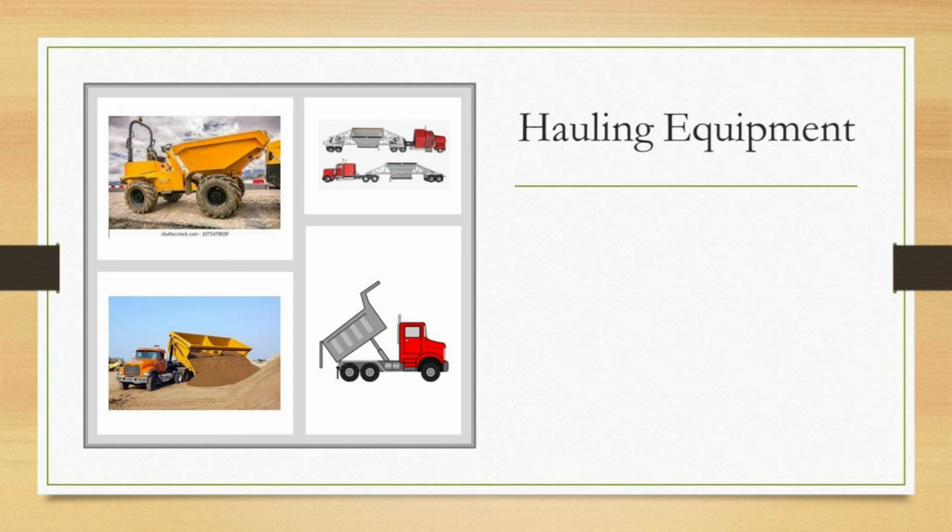Equipment used for transportation of material is known as hauling equipment, or simply haulers. Haulers may operate on roadways or railways, and are also involved in transportation of building materials, carriage and disposal of excavated earth, and haulage of heavy construction equipment. These are classified on the basis of the method of dumping the load, which includes dump trucks: side or rear dump trucks, bottom dump trucks, and dumpers.